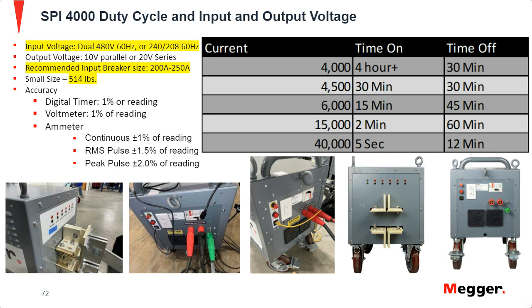It asks, what is the smallest size breaker that's required to be primary injection tested? For that, you can test motor case breakers all the way down to 10, 5 amps. It's all going to depend again on what you're trying to get out of it. Are you trying to test it? Is it a critical application? What does your company want to do?